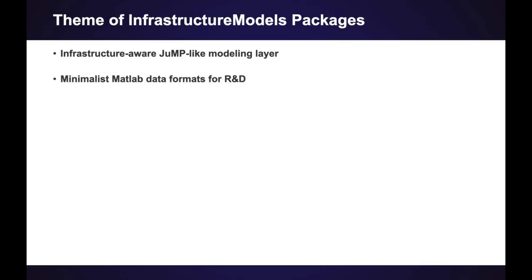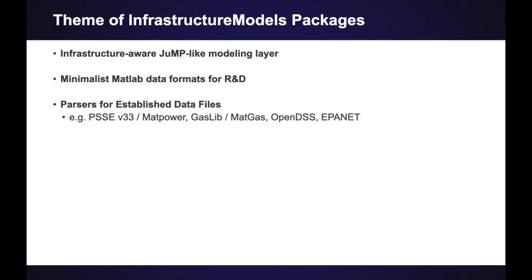Additionally, we have minimalist MATLAB-like data formats that are really useful for R&D purposes, but we also develop parsers for established data files like PSSE, which is an industry format for power transmission. MatPower is a popular academic format for power transmission. We have GasLib, which is for gas network R&D. We also developed our own MatGas format for gas transmission networks in a MATLAB type of design. We also support things like OpenDSS and EPANET, which are industry standard formats for their respective sectors.